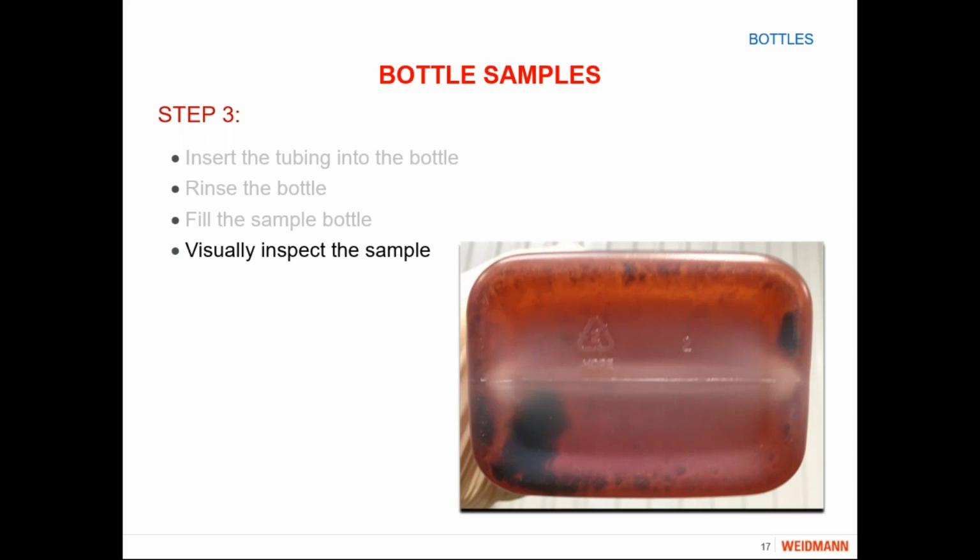But you're the first test when you pull that sample, because you're the first one that can look and see what the oil looks like. Do know that if it comes out too dark or if there's too much contaminant in it, most labs won't be able to do many of the tests that you may be asking for, because if it's too gunked up, it will wreck the sensors on the test equipment. It'll force them to have to shut down that equipment and spend a fair amount of time flushing out the equipment, cleaning out all the debris that was picked up from that bad sample, and then they have to redo their calibration checks before they can go back to productive testing again.